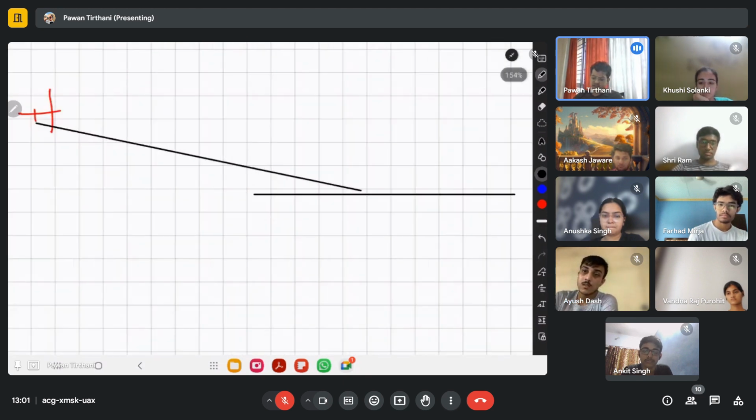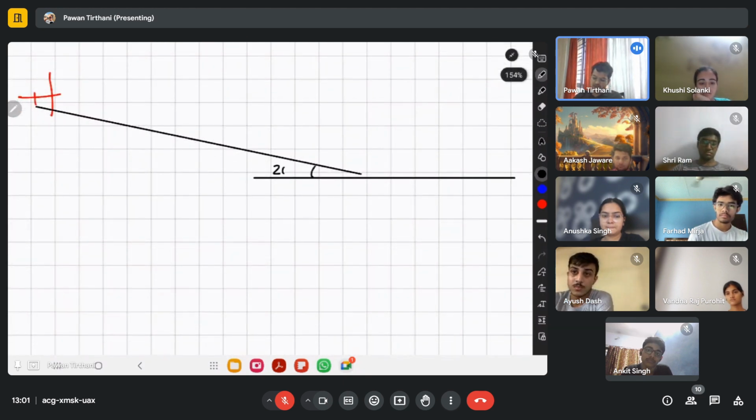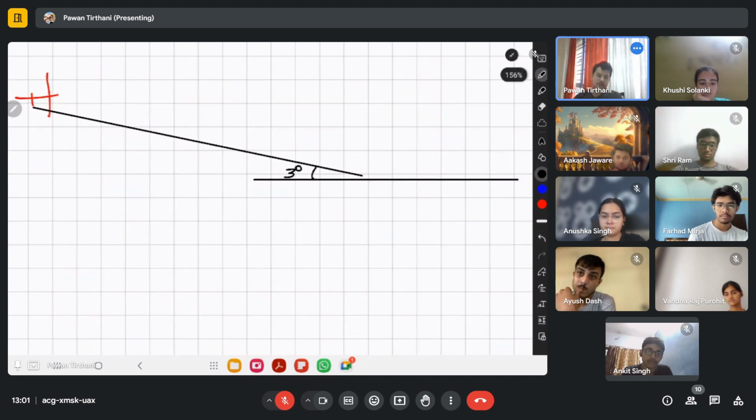Do you know what is the angle of this path? Do you think it is 20 degrees? No, it is a very, very shallow angle. It's a 3-degree glide slope. When you start flying, you will be taught how to visually see the runway and understand whether I am flying 3 degrees or not, based on visual features, based on how the runway is looking.